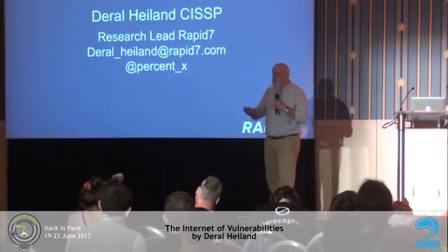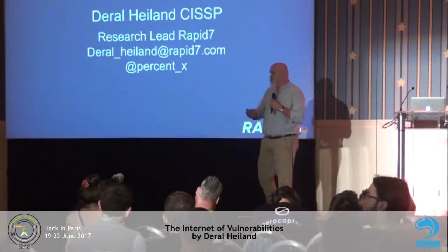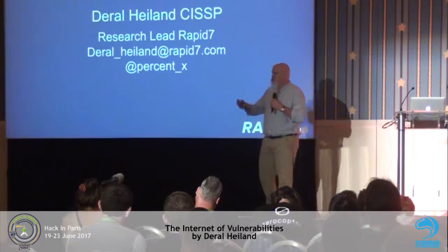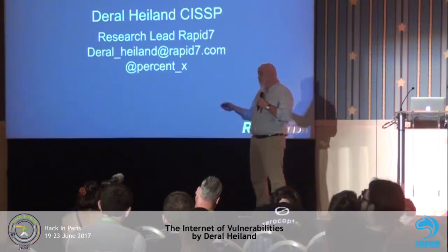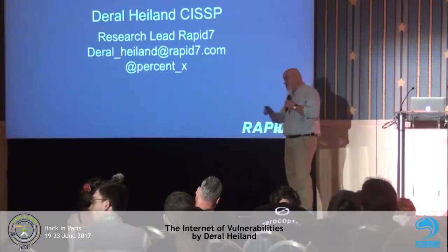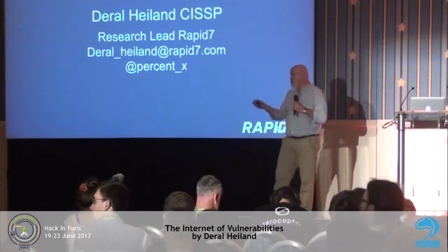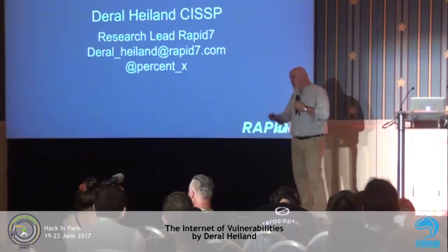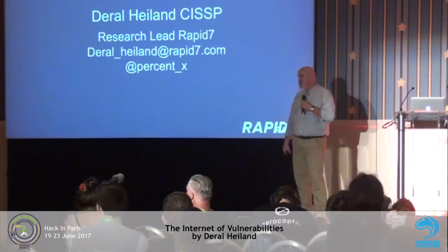Are there any exposed JTAGs, serial wire debug? Does it have any SPIs? Is there a UART in there? And then we'll go through that process and try to test for all those. Am I successful? A number of times in the cases with those, it gets really frustrating, really time consuming. But that's the typical approach that I take. And like I said, I've got one at home I'm doing that with right now.